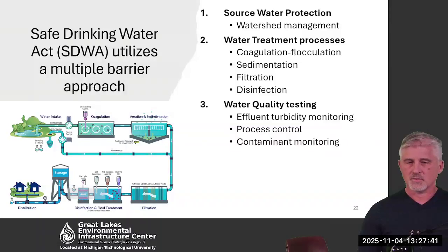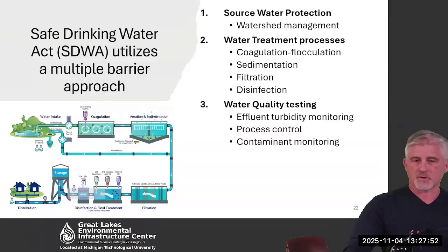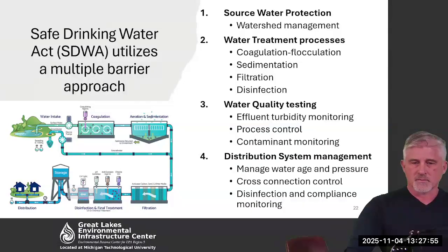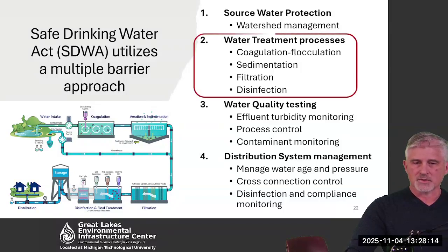Water quality testing can also be a barrier to bad quality water or microbes getting into the water. And then how we manage our distribution system also matters, with water age and pressure, having a good cross-connection control program, our disinfection, and how we meet our compliance monitoring. These all are part of this multi-barrier approach. So now we're going to briefly look at the water treatment processes.